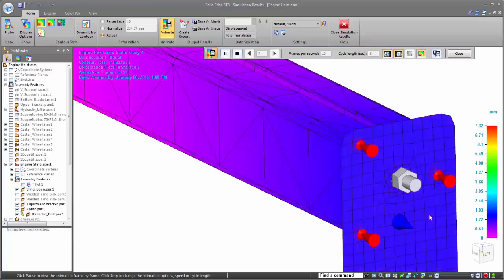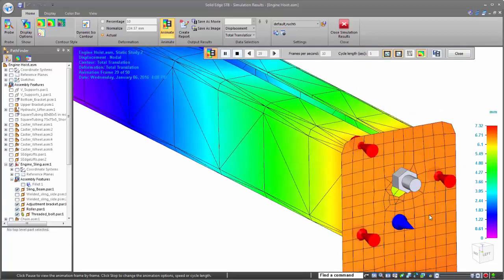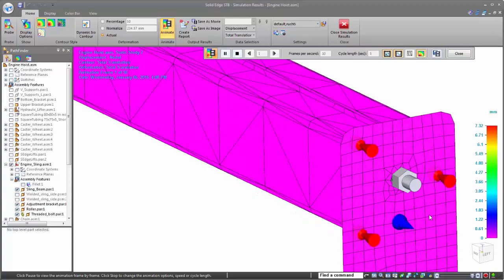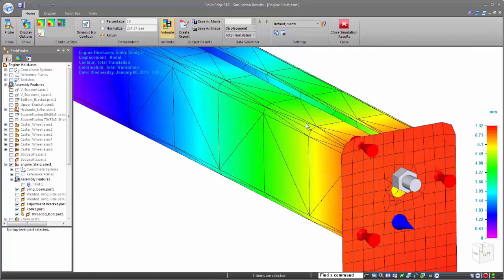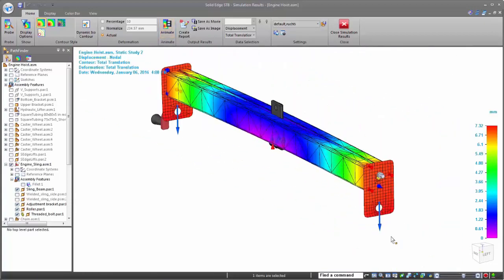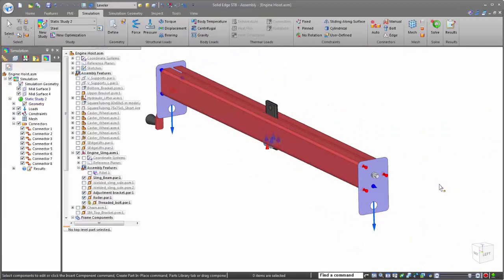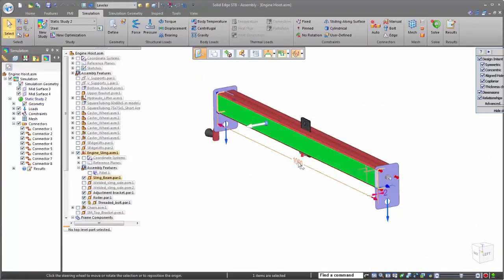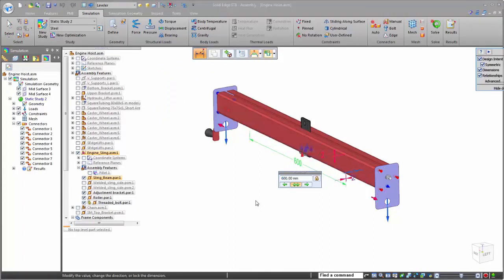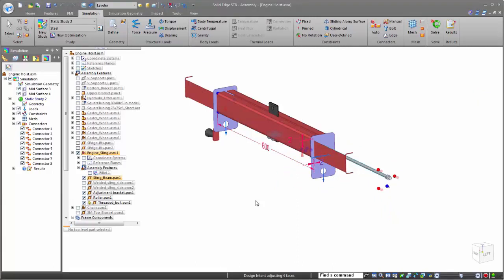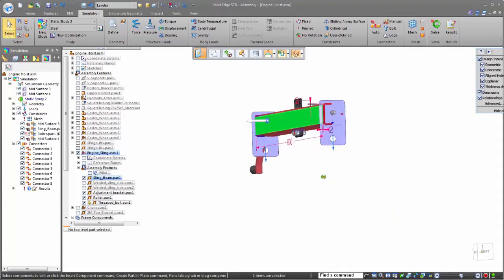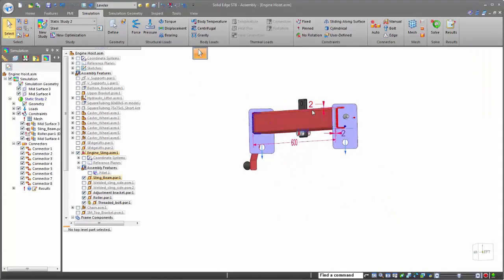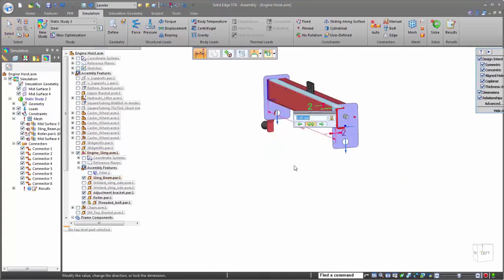We have a requirement that deformation cannot be more than 1 millimeter when fully loaded. Of course, working inside of Solid Edge with synchronous technology allows us to make any geometry changes we'd like in order to figure out the best solution to ensure that our deformation isn't too high or that our parts aren't too heavily overbuilt. We can simply input whatever values we wish to try for the dimensions and then watch the model update accordingly, all while keeping association with the simulation study features.